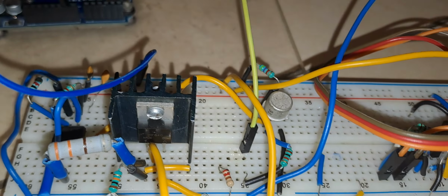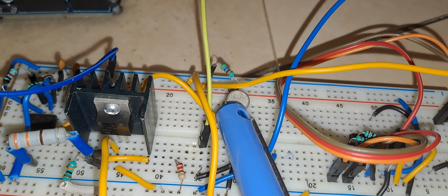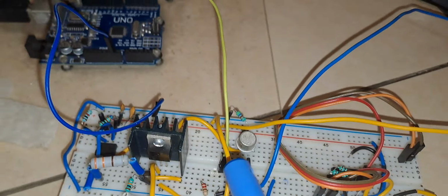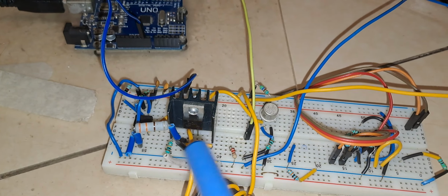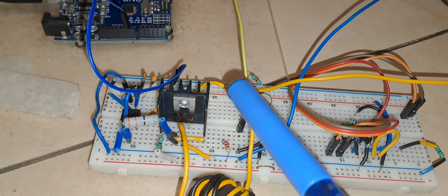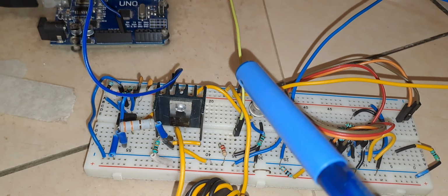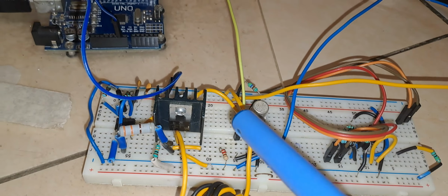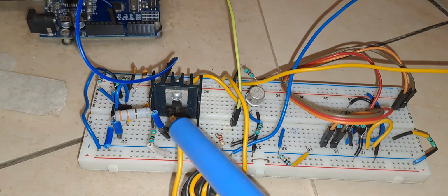These two signals are multiplied in this circuit. The modulating signal is fed in front to this transistor base, and when it is mixed, it generates a frequency based on the multiplication of the two frequencies. As we have seen in the previous video, we got a frequency of 24 kHz. Now I am going to demonstrate how the circuit exactly works.